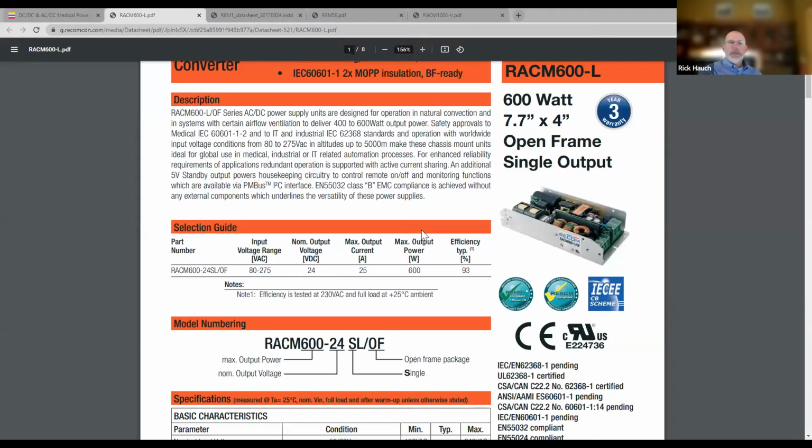That's definitely where the industry is going. What is going on in the semiconductor world is that faster switching speeds allow for smaller transformers. Look at what a 600 watt power supply was 20 years ago. I'm sure it was at least twice the size it is today.